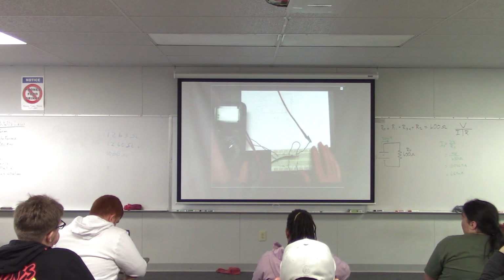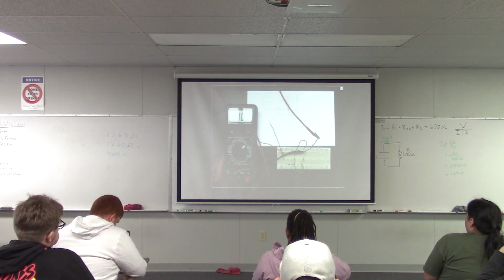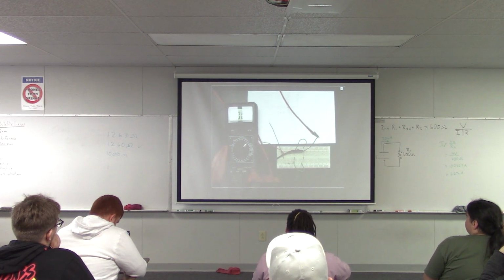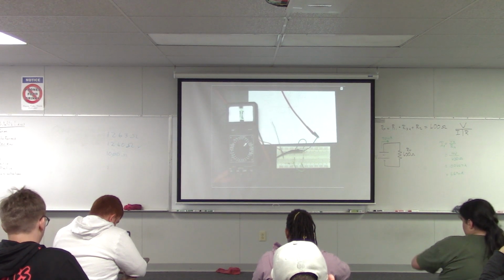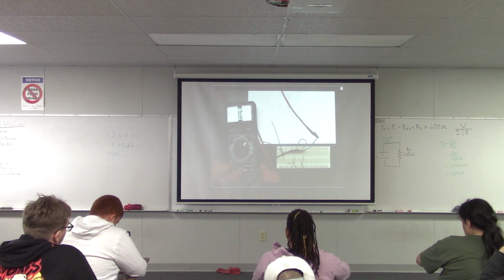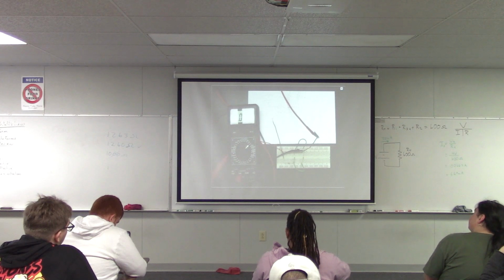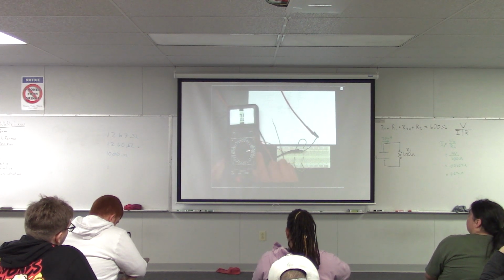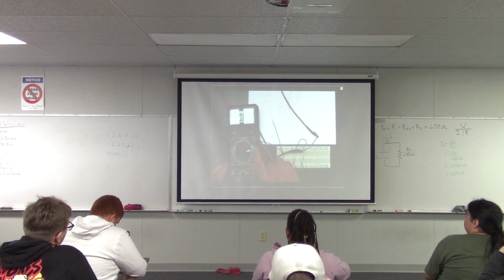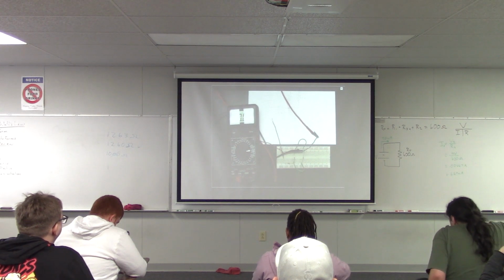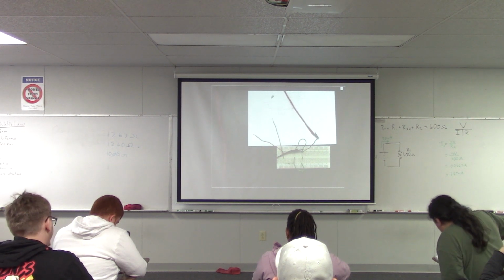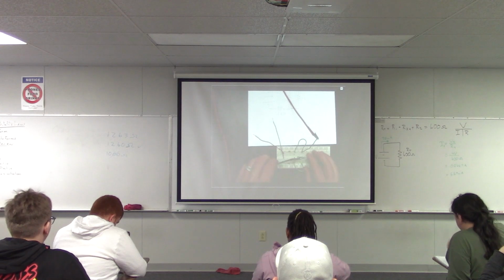Now, when you're measuring current, the meter needs to be in current measuring mode. So that means you need to move this red lead from the voltage port over to the current port. The black lead stays in common like always, but the red lead moves over to the current port, and you put the dial into the current measuring setting. So that's one of these two positions on the right-hand side. And now you're measuring current. So you measure current there.